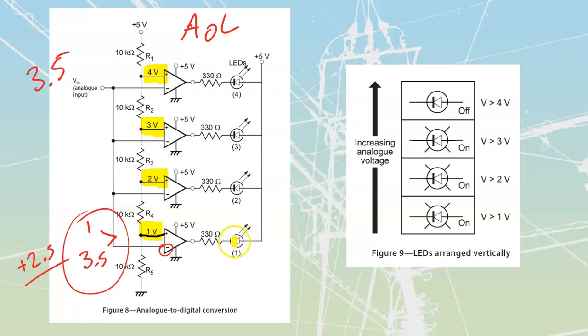We got an LED in here. It's properly biased, anode to the top over here. The 330 ohm resistor in there is just a dropping resistor for my LED. That's my first one. We'll go up to the next one.